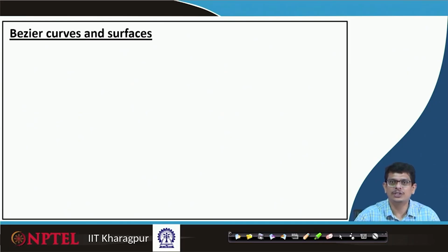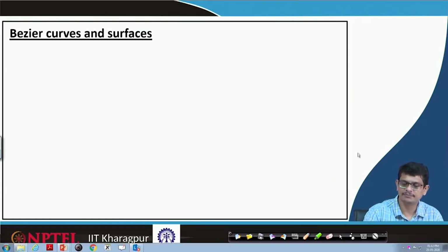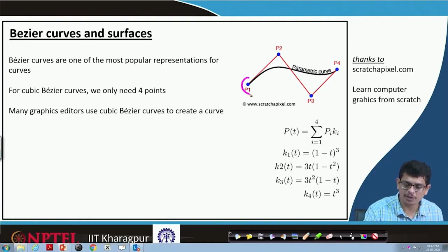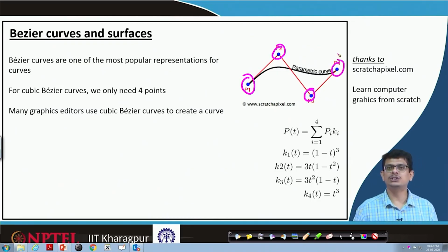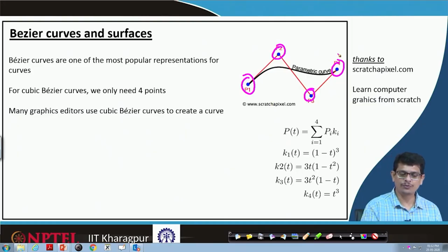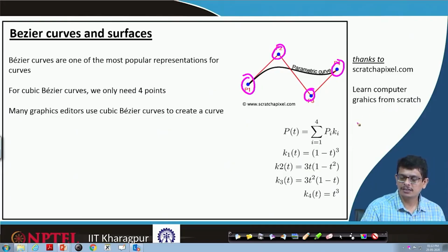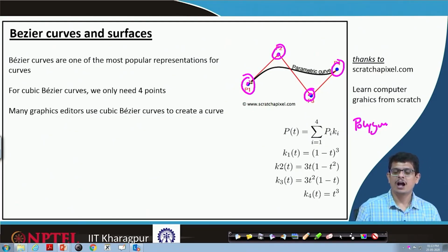There are other ways of constructing surfaces also, those are called Bezier curves and Bezier surfaces. In that, we have particular data points like P1, P2, P3, P4. We do not straight away join these data points. What we do is, we construct certain polygons fit in between these data points. And when we are fitting these polygons, whatever the curve which passes through that, crossing these polygons, that is what we call Bezier curves.